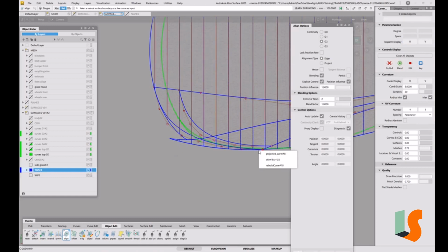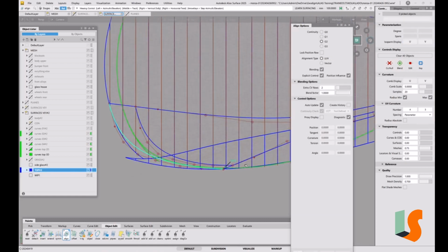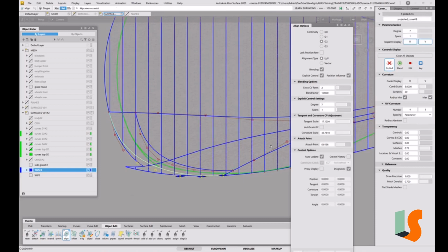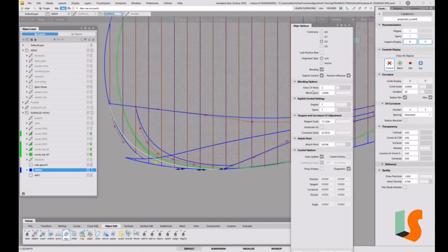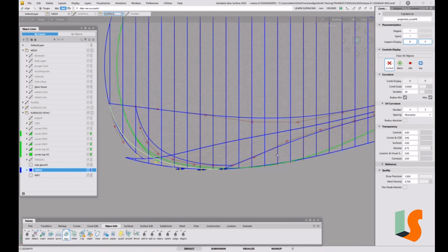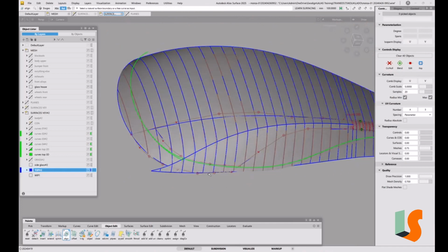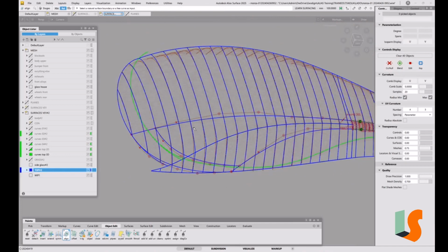It may not make much difference, to be honest, but if I go into that end and align that to this edge, and we go top, so with blend on, it's affecting those 2 points. The difference is probably very, very small between that and not having the blend on, and we're fussing really, because this is so far down here, we don't know whether this surface is actually going to give us what we want at all anyway. So now I want to put in a square between that edge and these curves here.